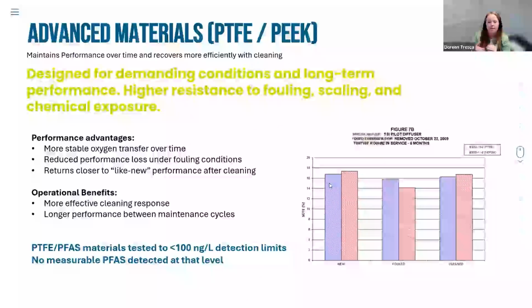The PTFE, once they're cleaned, they perform much closer to their like-new efficiency than the EPDM membrane. So that's a huge thing, especially if you're looking for a system that's going to last. Yes, it's going to cost a little bit more money up front, but you're going to see that in operational savings over time. So the benefit isn't just the lifespan, it's how the system performs between cleanings as well.